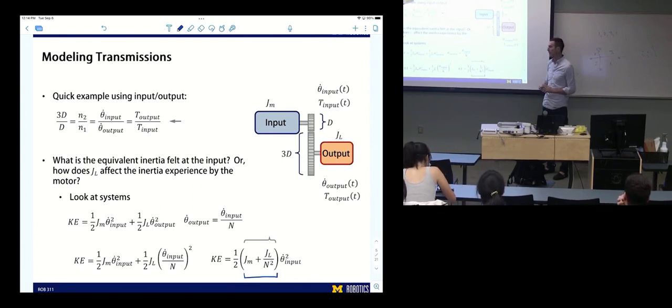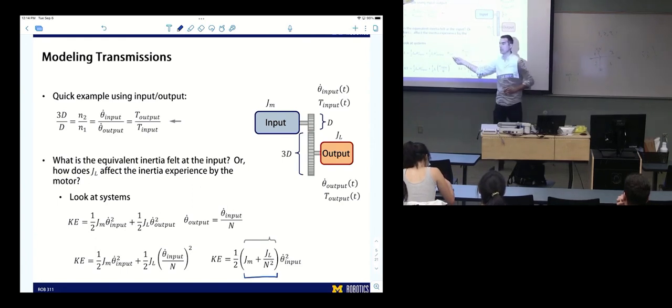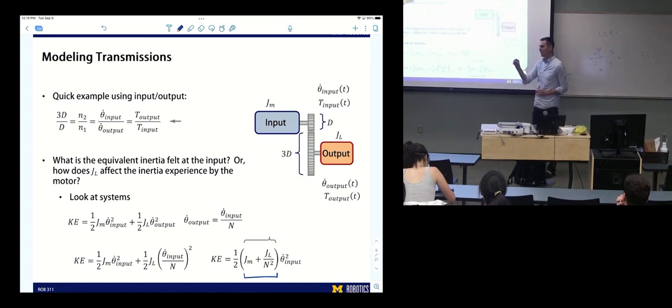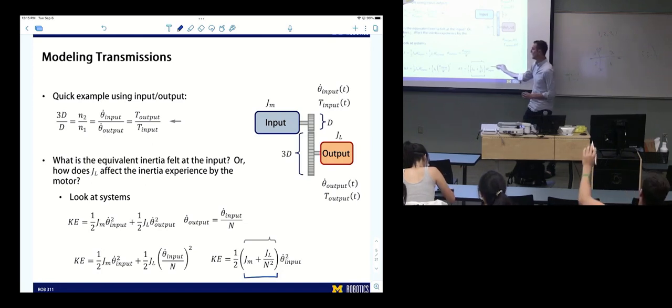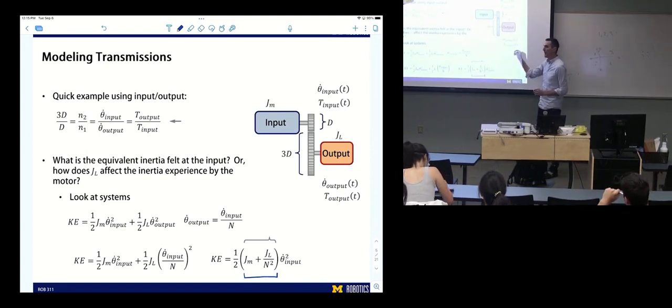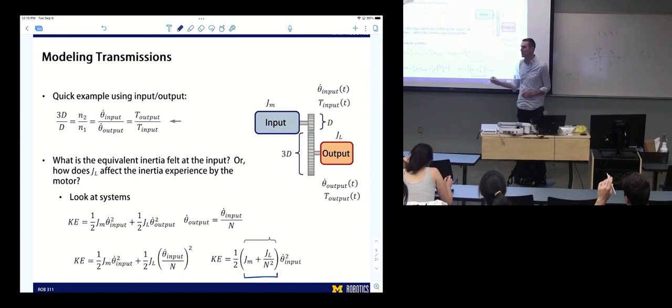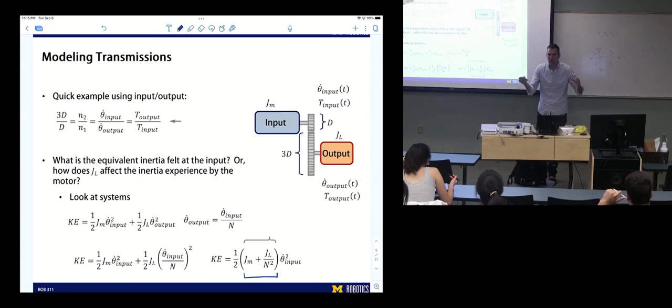Yes. So what happens here? This relationship will get reversed. We put it in terms of the output. Wouldn't the ratio instead of 3 to 1 be 1 to 3? So it will flip the ratio, and the square will make the load inertia weigh higher. It will make the motor's inertia way higher. That's right, because we would be rearranging these. It would make the motor's inertia n squared heavier. Or really n squared more rotational inertia, so more rotational mass.